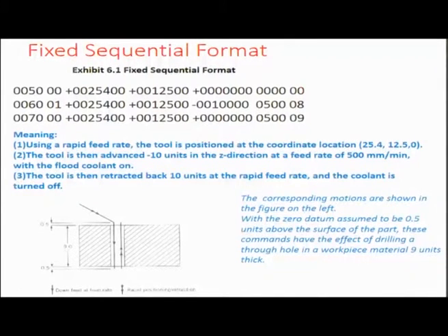The first number in this particular format signifies the line number, and you can see that there are some spaces left over, at least 10 spaces between the first and the second number. One reason for that is that people can add as many lines as possible without jeopardizing the whole code, because when the controller reads, it reads an increasing sequence of numbers. That is one very big advantage of the system.